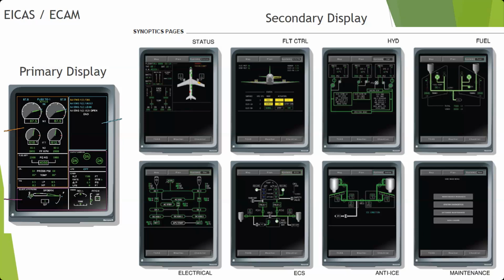But yeah, that gives us all our information, and this is all interpreted, right? The computer can turn lines green. Yep, that's normal. You've got a white line here. It shows the essential bus can get power from bus 1, but normally it gets power from bus 2, and it's green, okay? So it interprets that view, rather than you having to figure out whether the essential bus is getting power where it normally would. If it's set to bus 2, is that normal? Is it not normal? Well, we know it's normal on here because it's green.